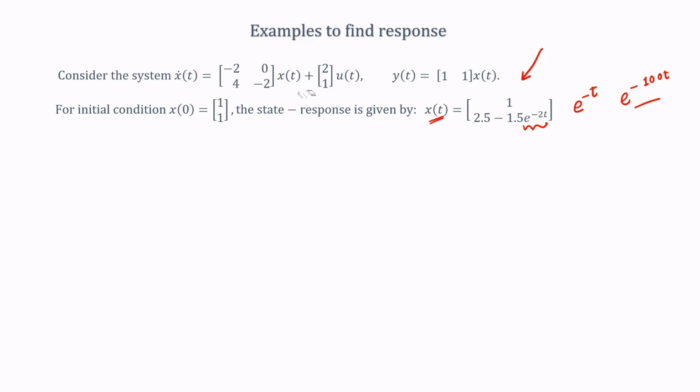So, if I change the eigenvalues of the state matrix, then I would be able to influence the state trajectories as we want. In other words, I want the state trajectories to have terms like e to the power of minus t, which means that I would want my state matrix to be somehow changed to have an eigenvalue of minus 1. Now, how can we achieve that?